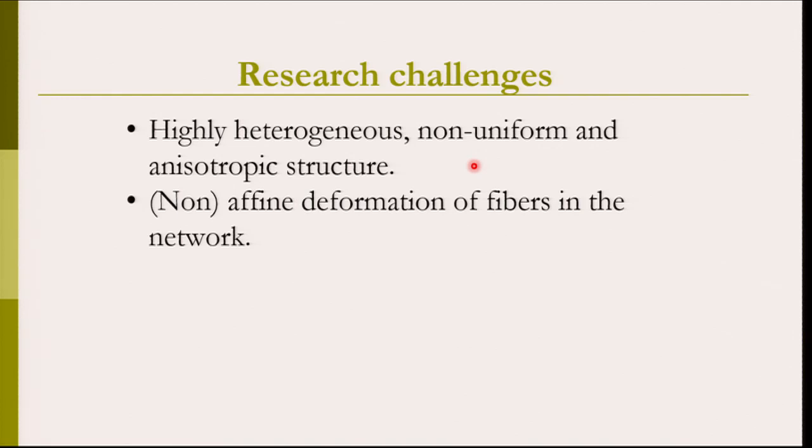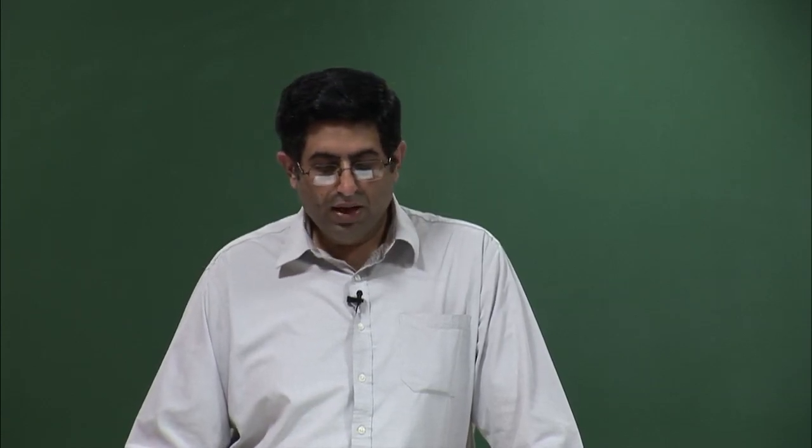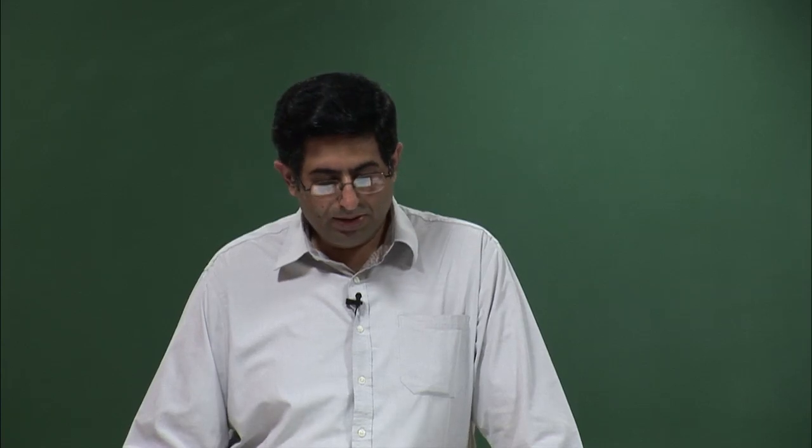For example, in a tensile mode of deformation, we presumed that there exists a relationship between the fiber and fabric strains, which is purely analytical in nature, but this may not be the case every time. So, this means we presume that the average load which is acting on the fiber to fiber contact is the same throughout the structure, but it may not be the case for highly disordered fibrous materials.